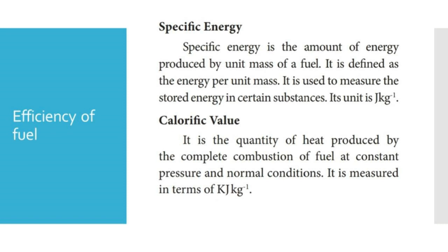Next, for methane, the calorific value is 50,000 kilojoule per kilogram. Then for CNG, it is 50,000. Then for LPG, it is 55,000. Next, for biogas, the calorific value is from 35,000 to 40,000. Then for hydrogen, it is 1,50,000 kilojoule per kilogram.